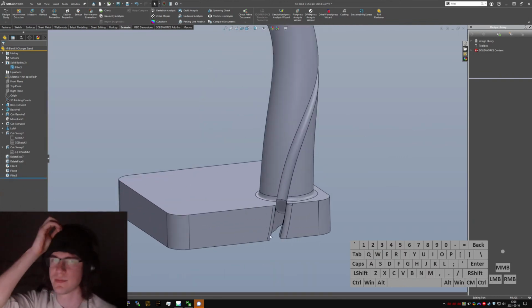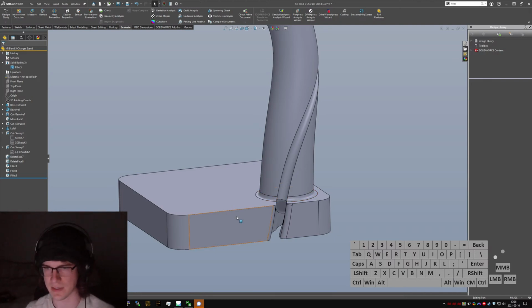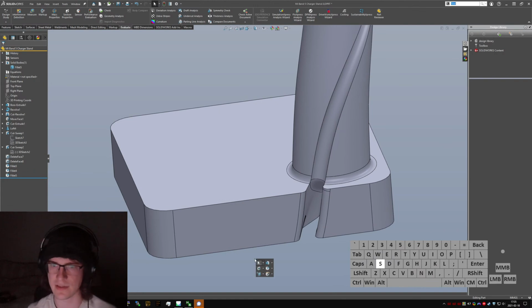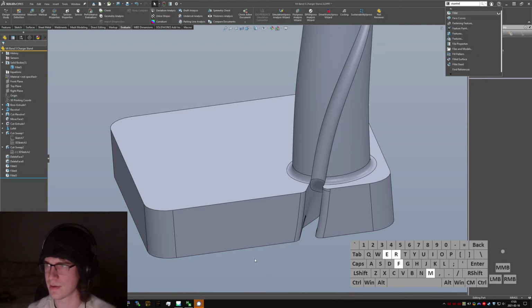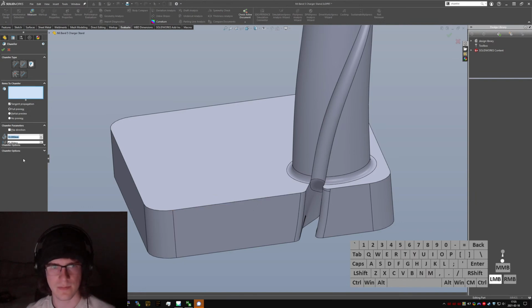Sometimes it matters to make sure that you can't do like 1.5 millimeter chamfers, because then it will be not layer lined and your geometry comes out not as nice. Super nitpicky thing, but worth caring about. Oops, just 1 millimeter, please. And do not do tangent propagation.